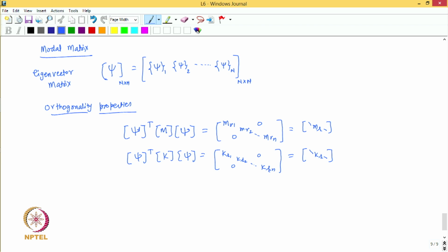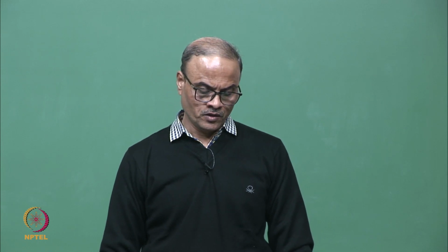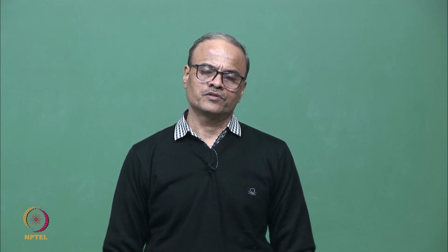So, that is how the orthogonality properties can be expressed in compact form, and these orthogonality properties play a very vital role in modal analysis, because they are going to allow us to decouple the differential equations, right. That is something we will see later.